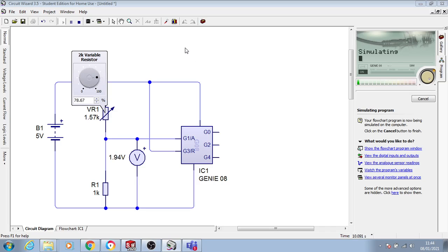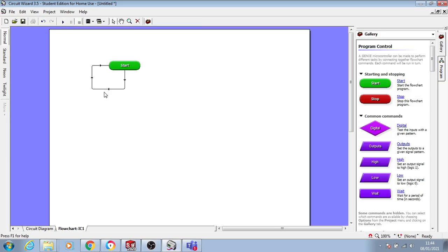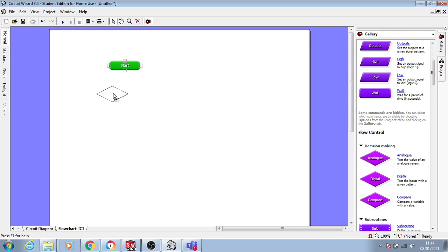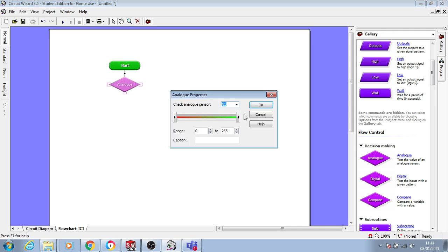Okay, so a really basic introduction to how to control a sensor, one of many different types of sensors, into a PIC chip. Now if you were going back to the flowchart, if we are to play around with that, what we've got here, instead of looking at a digital input read, we look at the analog input read here. Now what's happening here, instead of saying check the voltage, what's happened in the chip is something called an analog to digital conversion, ADC.